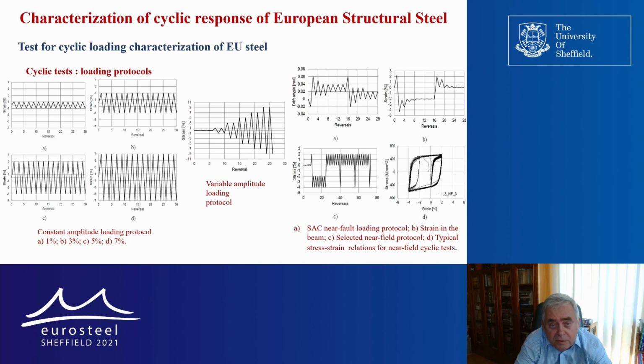Related now about the low cyclic fatigue of the same steel grades, we have done 3 different types of tests. We have used constant amplitude loading protocols with 4 different amplitudes of strain.